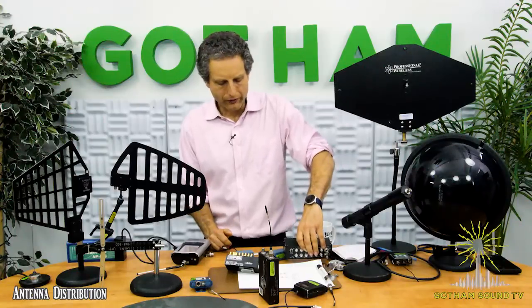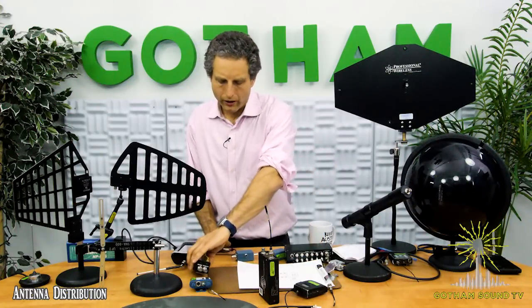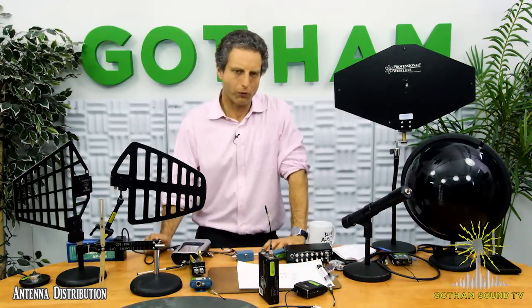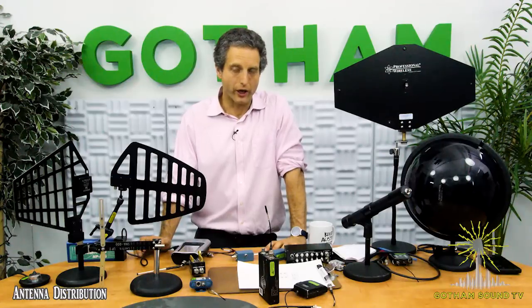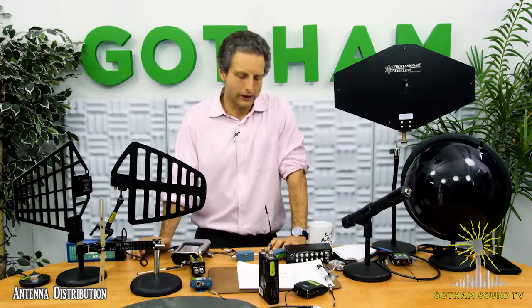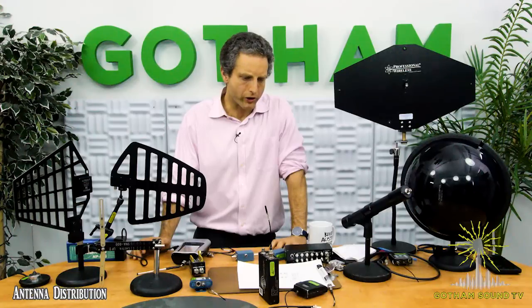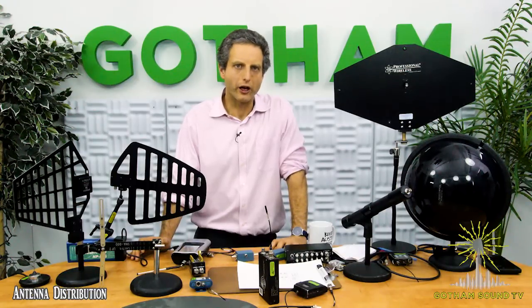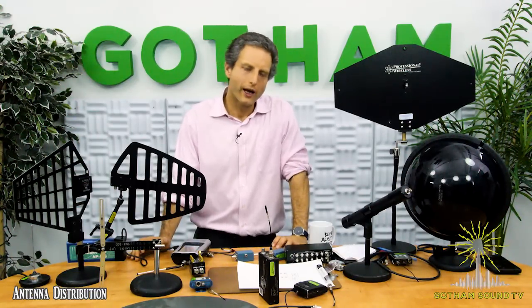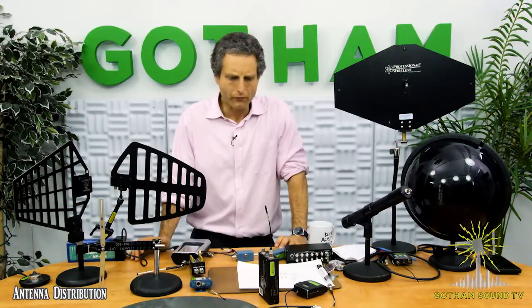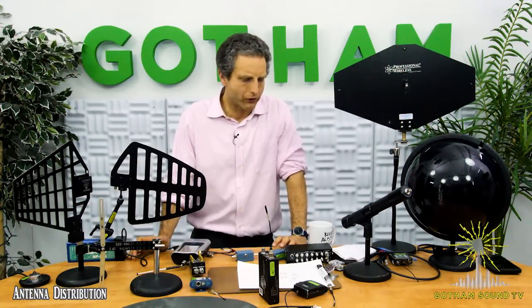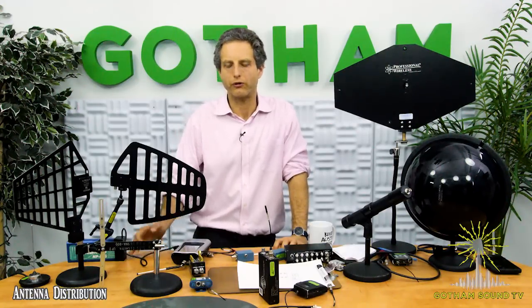So that brings up an interesting topic, which is that there is definitely a tension with wireless mics. The idea of going wideband is really great, and it's necessary, but when you go to such a wide bandwidth, you're bringing up the overall RF energy into the system, and that's not always good. Picture a walkie-talkie's RF energy, which might be close to a block 470. You need some pretty hard filtering in order not to overload the front end of a receiver.